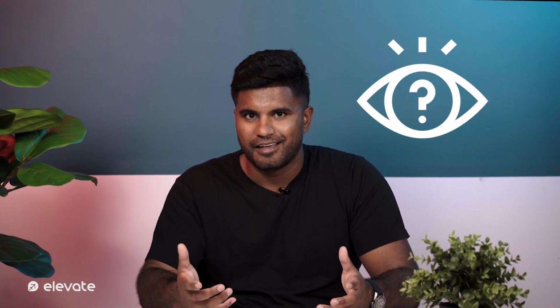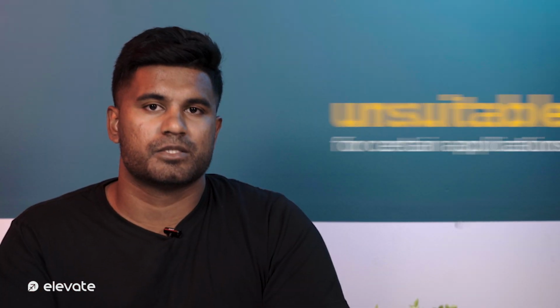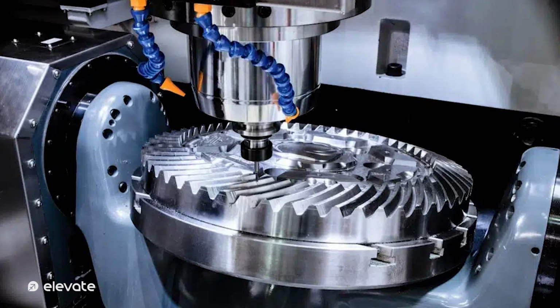In reality, the slippage occurs over a minuscule time frame, so it's not noticeable to the naked eye. But it does constantly slip and may bring about an ever so slightly varying rotational speed and torque, which make it unsuitable for certain applications. A good example is a CNC milling machine, which requires a high degree of precision. Now that's a fairly comprehensive overview of AC induction motors.